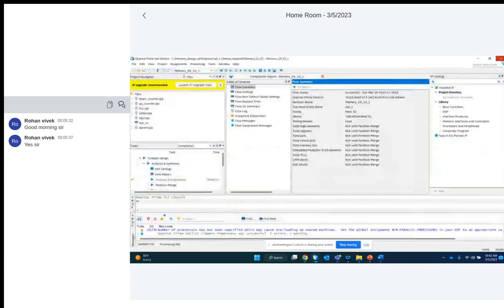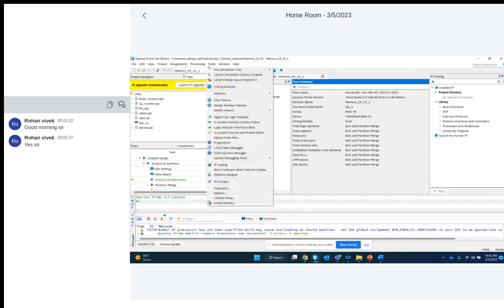Now we need to verify the functionality by the help of a test bench. Okay, now what we need to do, as earlier, we knew that whenever we generate a test bench component, that means you have a simulation component. How do we go ahead with this logic? Let us explore that now. So go to tools, run simulation tool, RTL simulations.